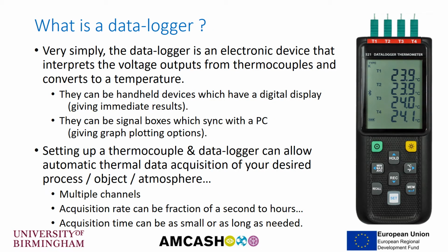And so what is a data logger? Well, very simply, the data logger is an electronic device that interprets the voltage outputs from the thermocouples and converts that to a temperature reading. They can be handheld devices which have a digital display on them, as we can see, and this would give you an immediate result. They can be a signal box which syncs with the PC, and that would store the data as a TXT file on the PC, and that gives us various graph plotting options.